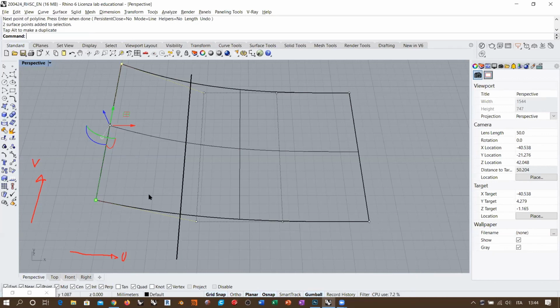Because this is one single span, inside one span we have 4 control points acting to determine the shape, because this is a degree 3 curve or surface or whatever you want. So if this is a single span, there is no possibility of having a local deformation, because all the 4 control points involved are affecting the whole extension of this span.